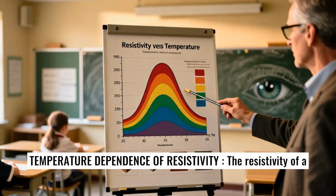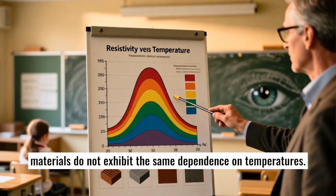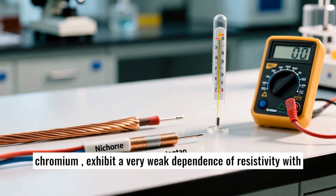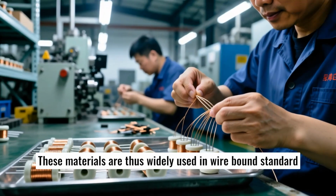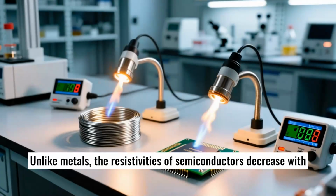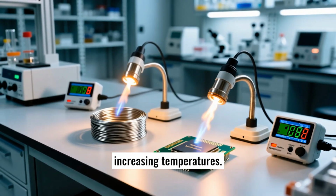Temperature dependence of resistivity. The resistivity of a material is found to be dependent on the temperature. Different materials do not exhibit the same dependence on temperature. Some materials like nichrome, which is an alloy of nickel, iron, and chromium, exhibit a very weak dependence of resistivity with temperature. Manganin and constantan have similar properties. These materials are thus widely used in wire-bound standard resistors since their resistance values would change very little with temperature. Unlike metals, the resistivities of semiconductors decrease with increasing temperature.